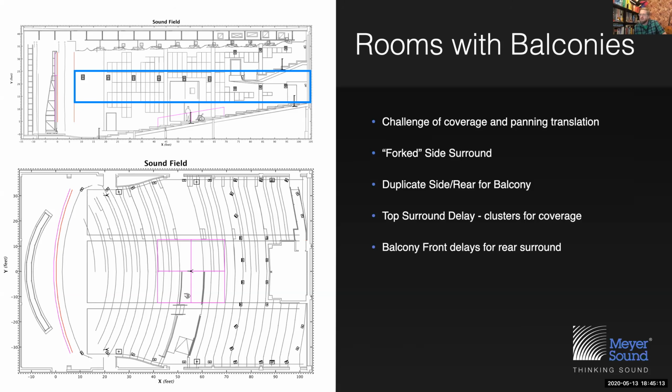But in this case, if this were only a 5.1 system, due to those different conditions, specifically the distance to the listener, as well as the distance offset of the physical loudspeakers, we would want at least two channels to deal with time alignment as well as equalization of those essentially subsystems of one channel of cinema content.